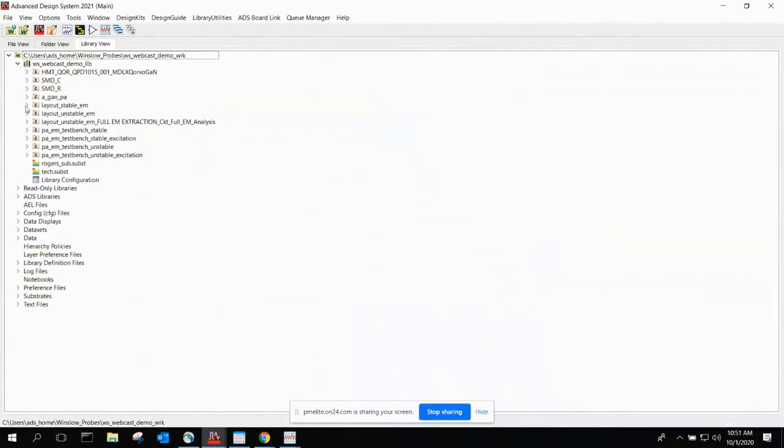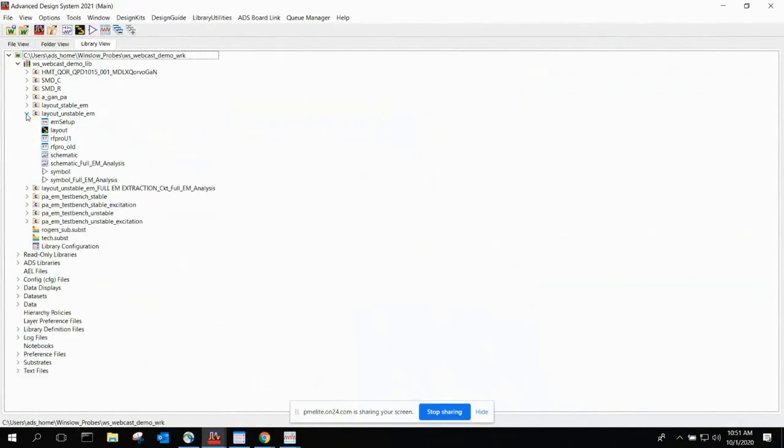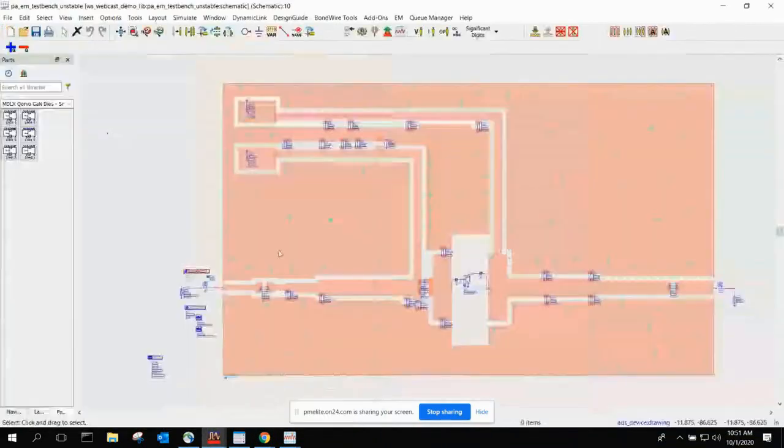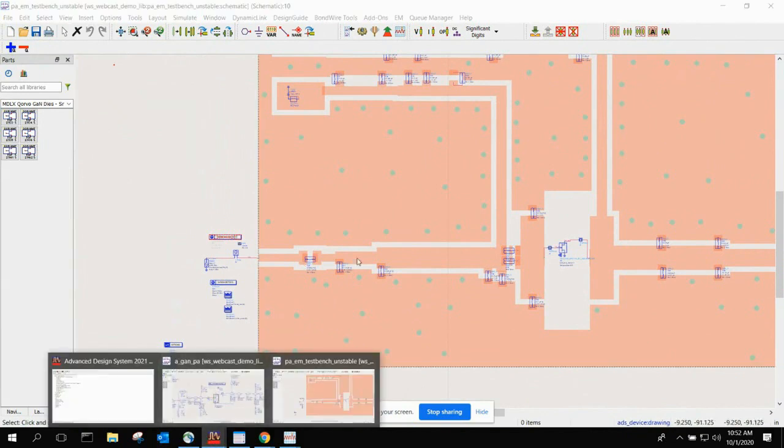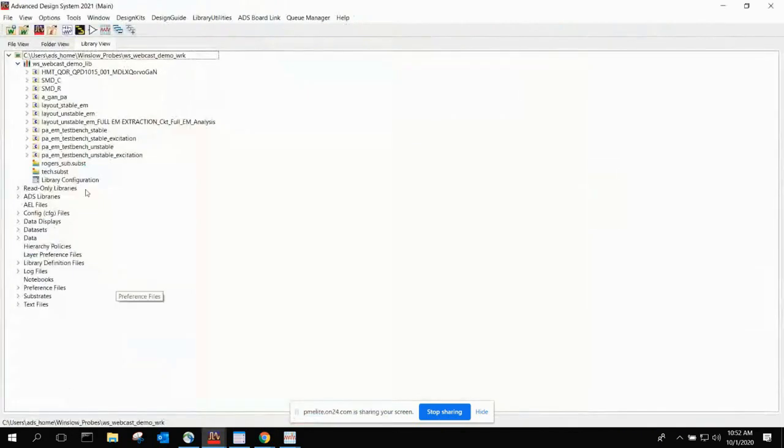Okay, so in the analysis, essentially what I do is I take this circuit, this unstable circuit, and I do a little different simulation. Instead of a harmonic balance simulation, I run an AC simulation. So I just ring this circuit with an AC signal at the input and just hit all the nodes with some kind of voltage. And I'm hoping that at all the frequencies, enough signal leaks through. Most of it bounces off the input, but I'm hoping that at some frequencies, some of this signal will get in here and stimulate for me a similar oscillation condition.